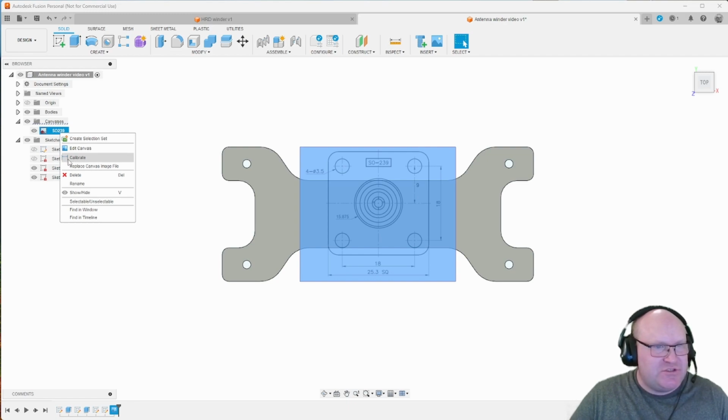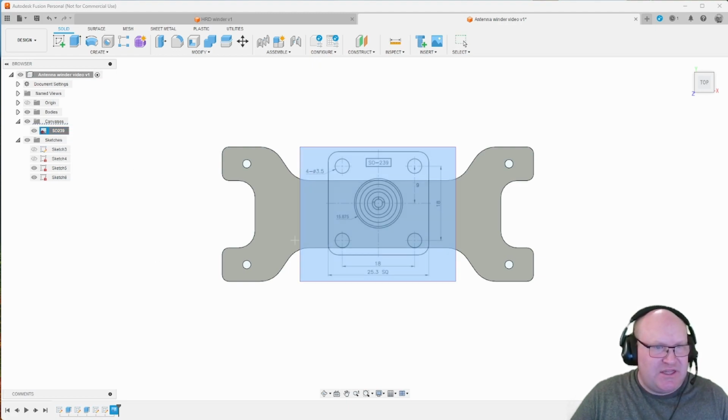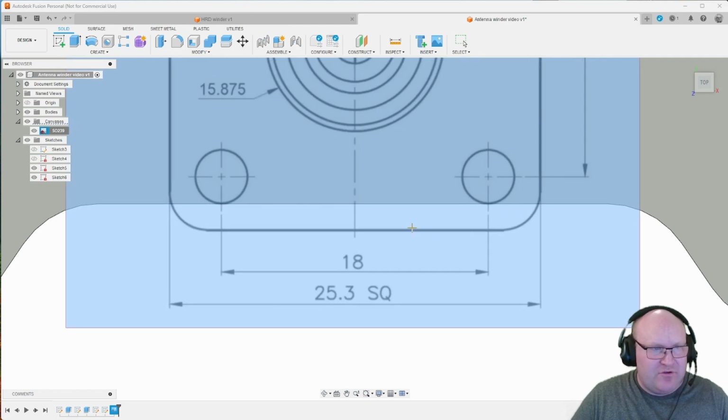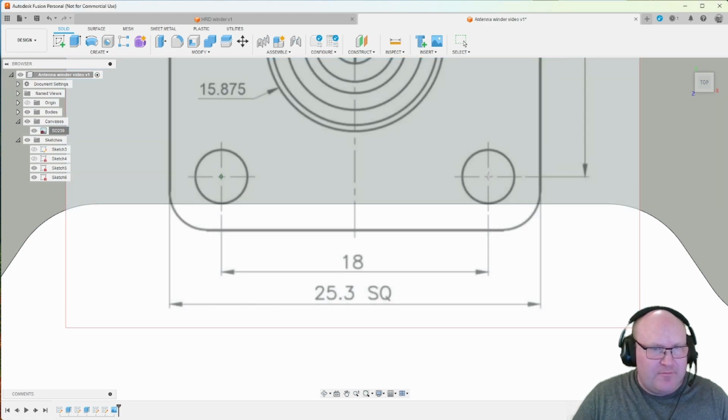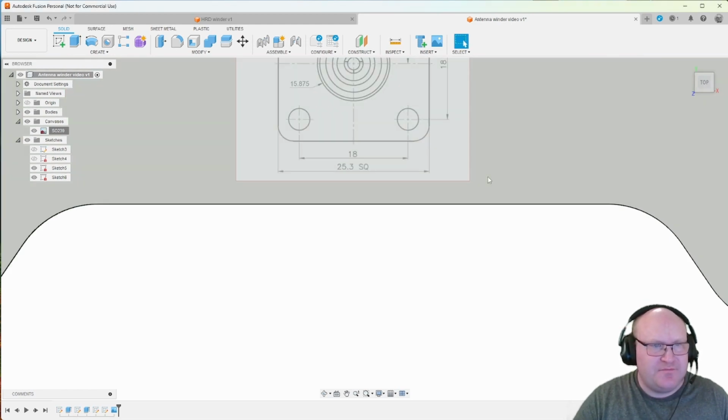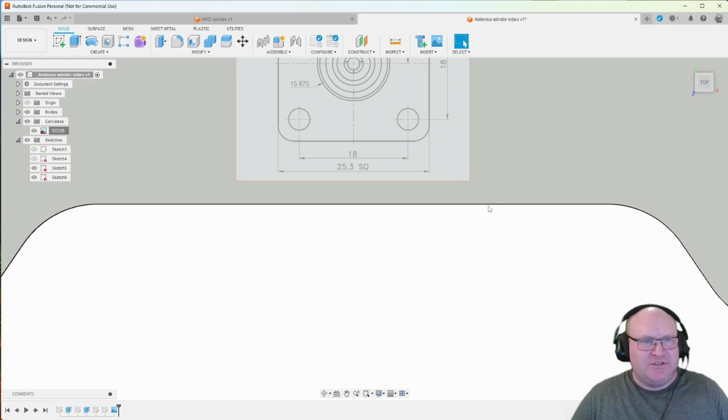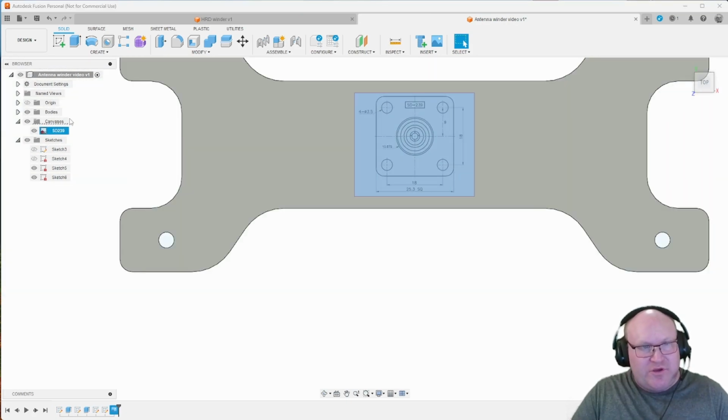Here you can see there's a dimension to it, and this one is really helpful because we already have a dimension. So let's calibrate this, zoom in so that you have a good measure, and place it between these 2 holes here. Just roughly click it above here to above here, and say that this is 18 mm. That will scale the entire drawing so that it's correct. This is something you can do with your own drawings as well. Just have some sort of measuring tape next to it, and make sure you take a photo that's directly perpendicular to it, and you can simply scale it.